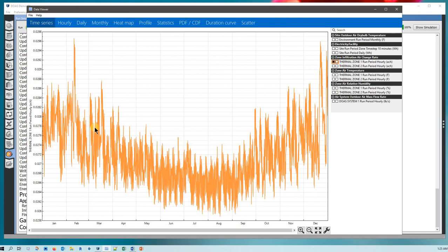It looks at the wind speed and the orientation of the building, and then estimates based on those factors how much infiltration is actually happening at any given time under those natural conditions. So it varies some, but you can see it varies within the range from about 0.26 to generally about 0.286, with one anomaly here where it got much higher, probably during a really high wind condition.